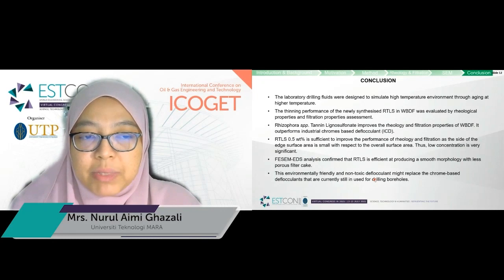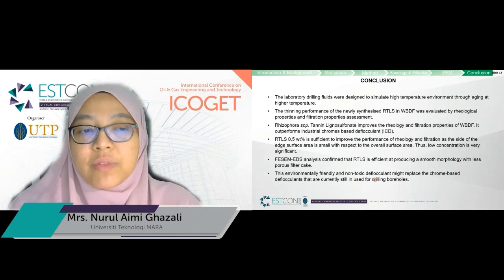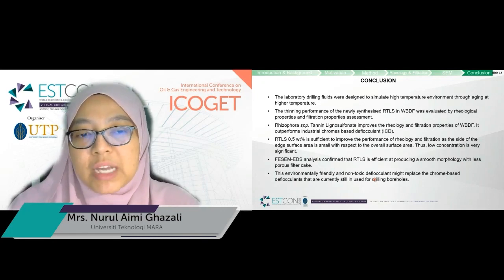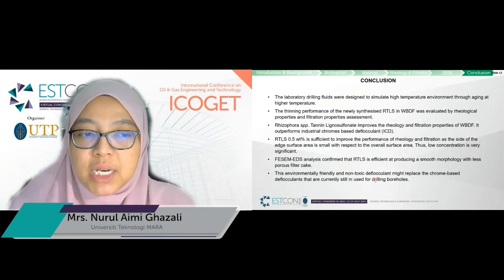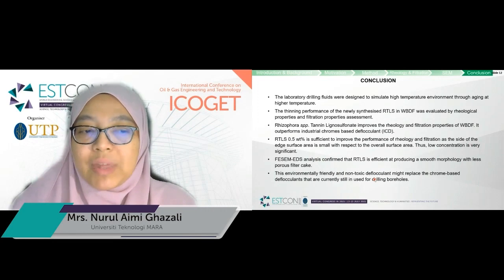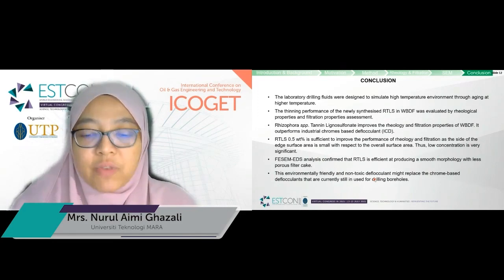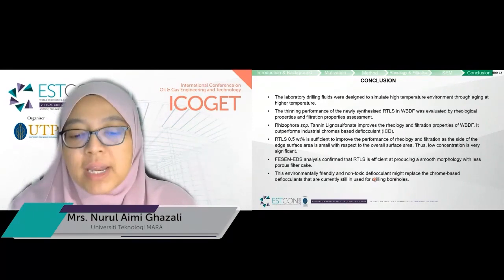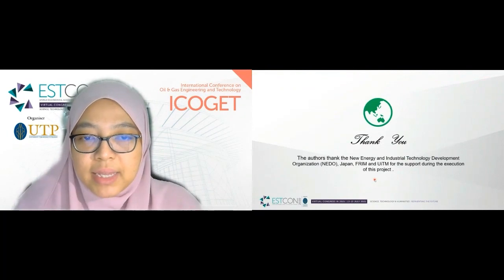RTLS 0.5 weight percent is sufficient to improve the performance of rheology and filtration, as the edge site surface area is small with respect to the overall surface area, thus a low concentration is very significant. FESEM EDS analysis confirmed that RTLS is sufficient for producing a smooth morphology with less porous filter cake. This environmentally friendly and non-toxic deflocculant might replace the chrome-based deflocculants that are currently in use for drilling boreholes. Thank you.